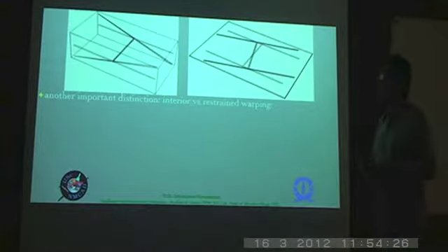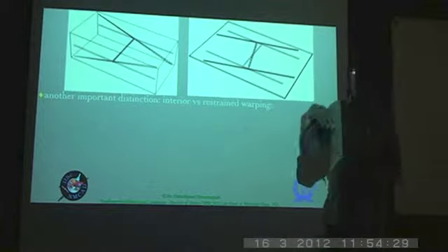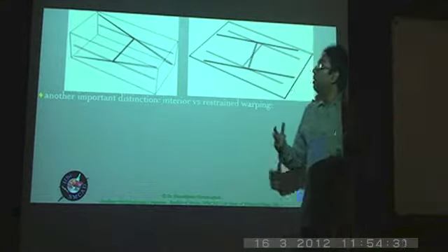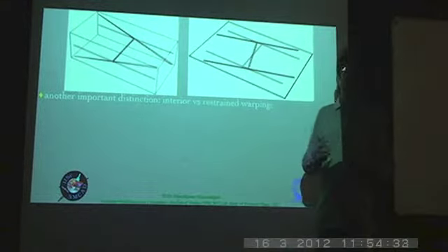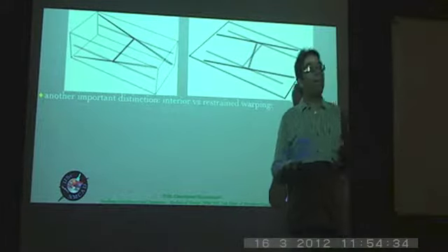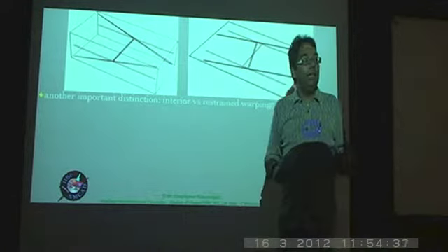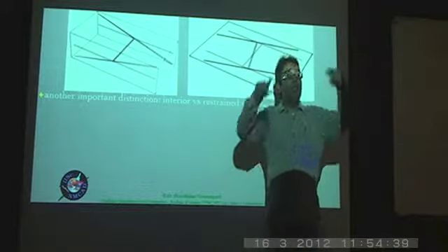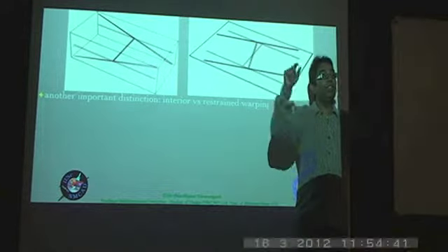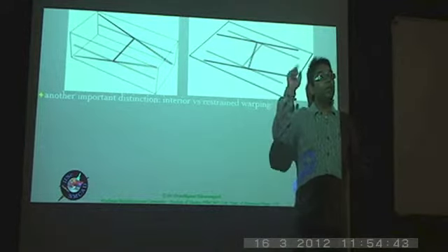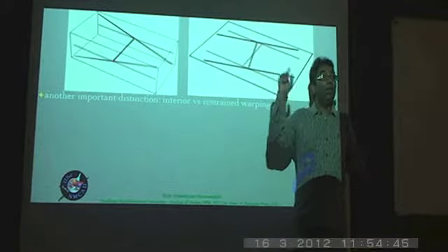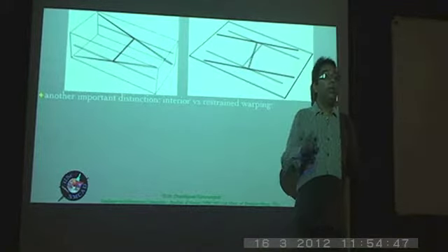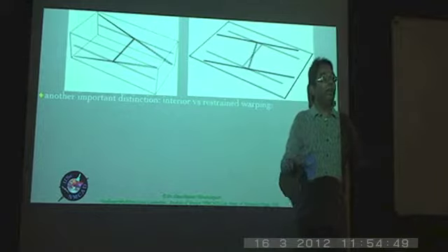So in such cases, for an I section, there is a problem related to the so-called bimoment, where you apply axial forces on the edges of each of the flanges. You have two flanges for an I section. One will be tensile, the other will be compressive, and it will be reversed in the bottom flange.